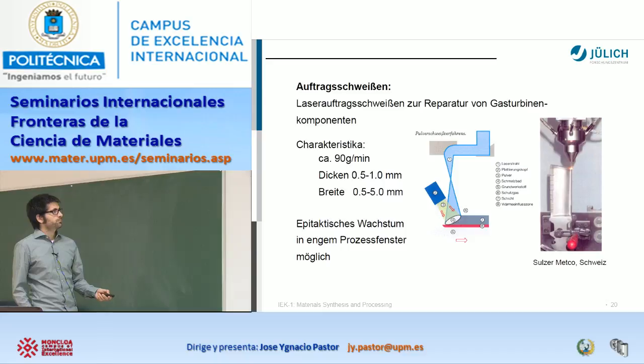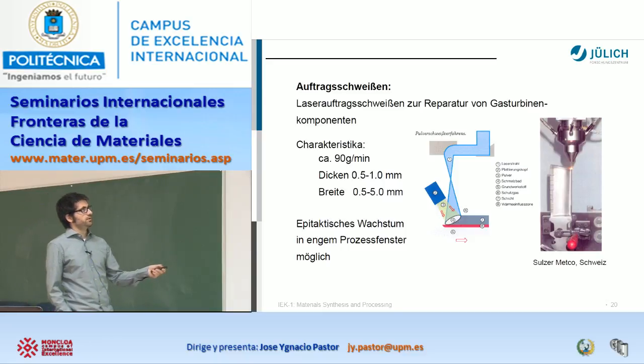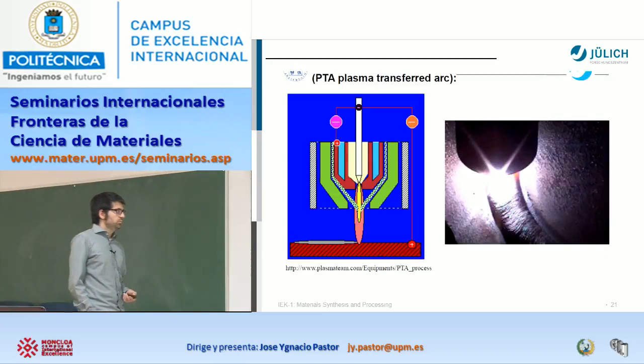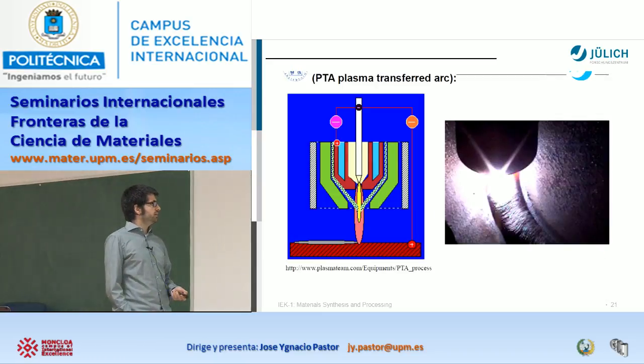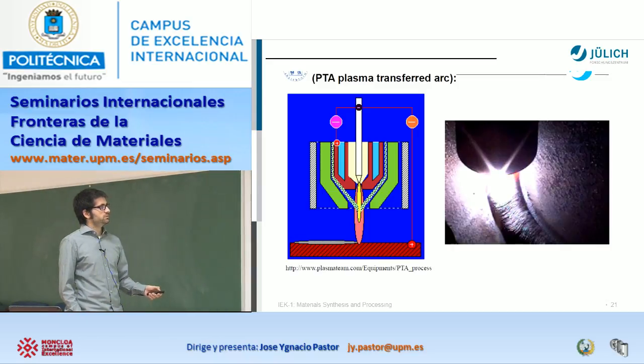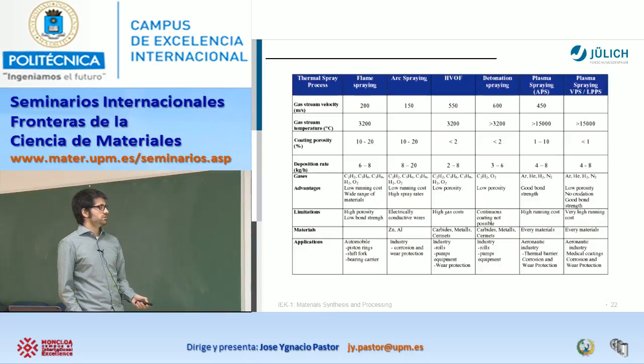Okay. Well, even here you can see the button for the gas turbine components. More techniques, but mainly based on the same principle. Also for repair technologies, but based on this plasma spray. Introduce your powder, again you heat it up, generate your plasma, and impact on your substrate.